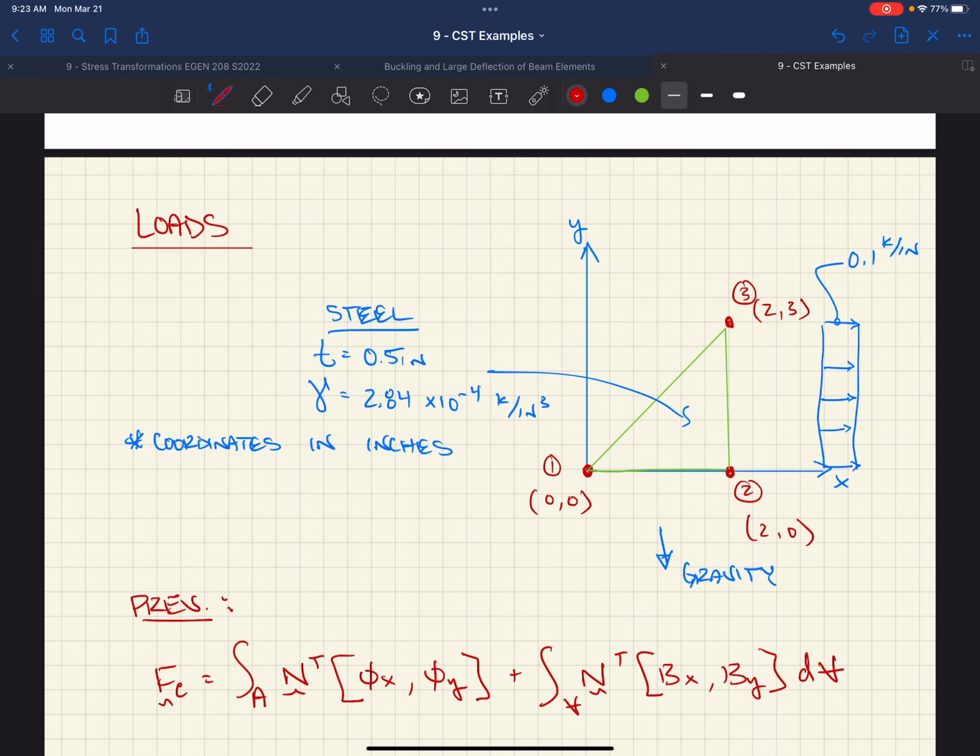This uniform load, as we've talked about, I think we did talk about this on Wednesday, right? What this load could be from. Could be a wind load that we're applying on the edge of our diaphragm. We decided to simplify our model. For instance, we're not going to model the walls. We're just going to simply apply a tributary width above and below a diaphragm to that diaphragm. So now we have, in this case, this might be on the leeward side of a wind loading case, right? So the wind is sucking on the back side of our building, pulling on it. And so we'd have this load that's pulling away from our element.